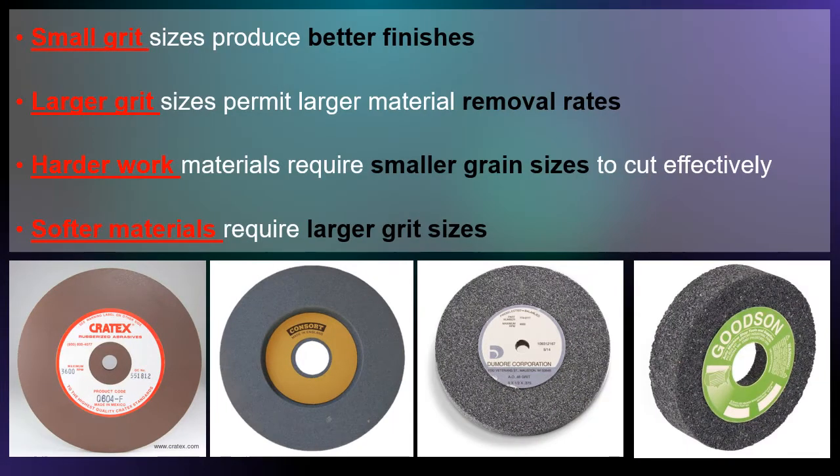Smaller grit sizes produce better finishes, and larger grit sizes permit a larger material removal rate. The harder work materials require smaller grain sizes to cut effectively, and finally, softer materials require larger grit sizes.